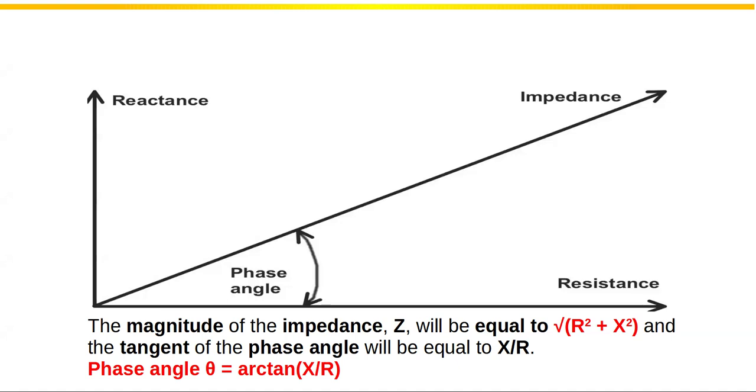It's just that in your house, when you have that, you're paying for a lot more power than you're actually getting. We'll talk about that a little bit. Because you're going to have some apparent power versus real power. And the real power is what's dissipated. The apparent power is what's happening in the inductance and capacitance, and it doesn't dissipate any energy, but it can draw more current from the power company. And they charge you based on how much current you draw. They don't care about your phase angle.